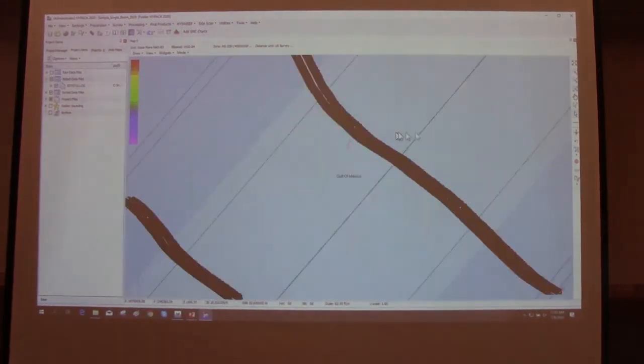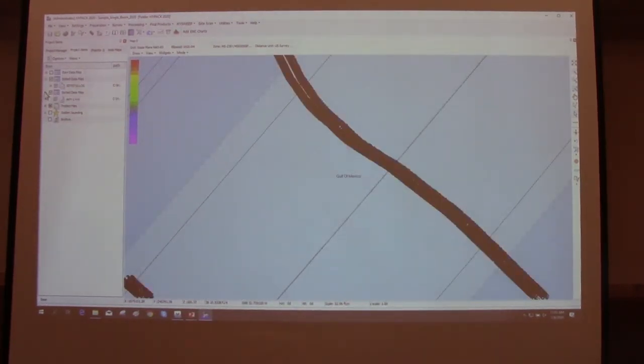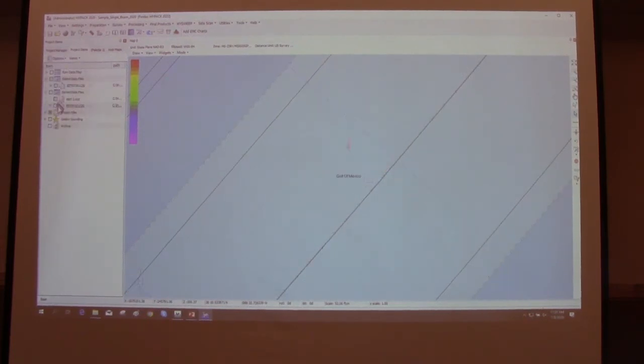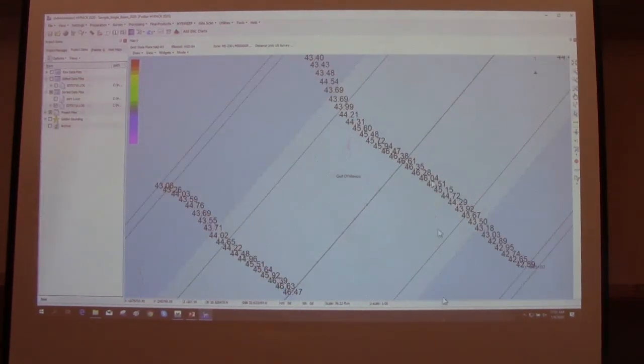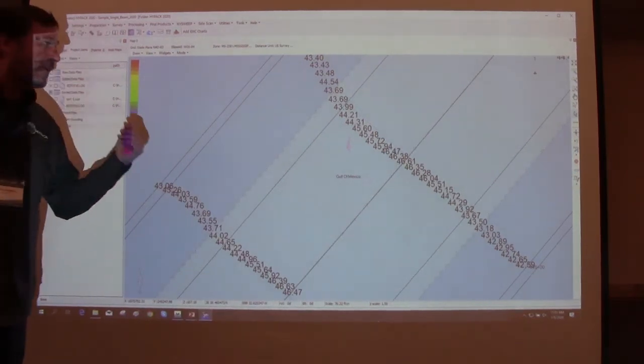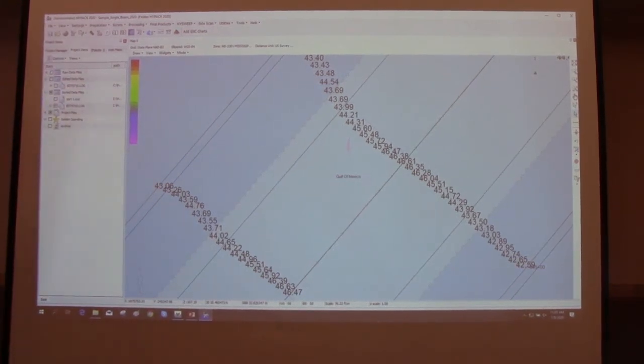we go. Okay, so there's my edited data. And there's the soundings every 25 feet. So you'll see you got the nice even soundings going across the channel. If you're looking more for that rather than the Soar program. But again, it's not prioritizing or choosing the shoulder sounding. It's using just based on distance. So that's another option here. Any questions on that?